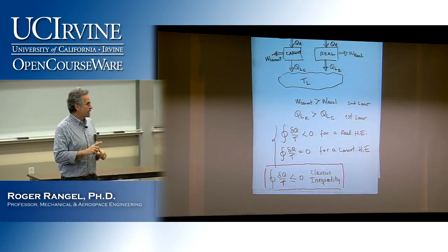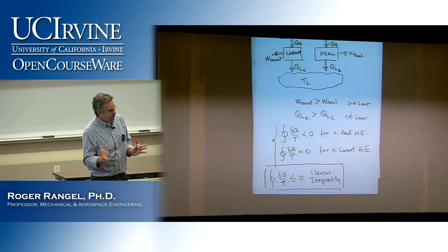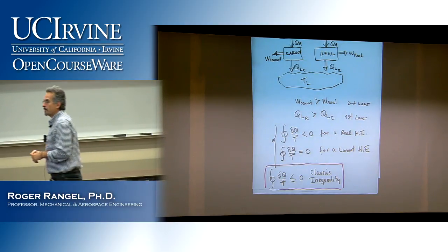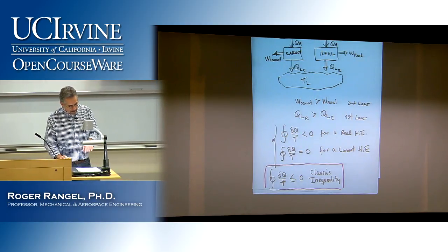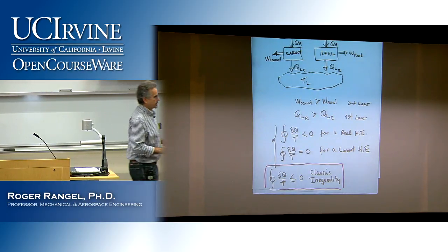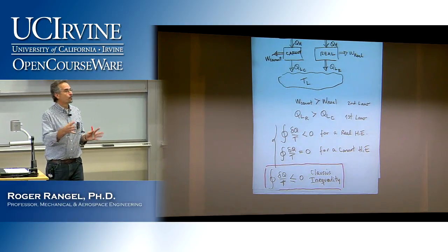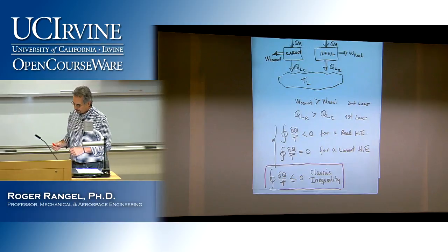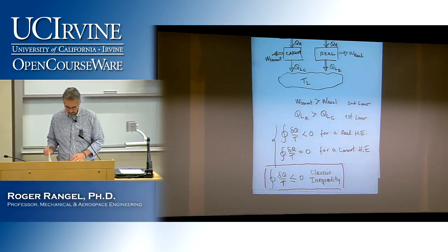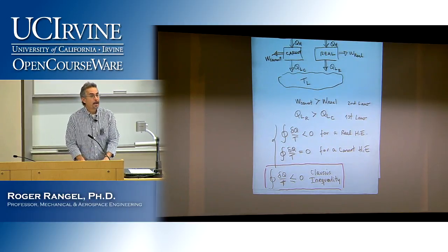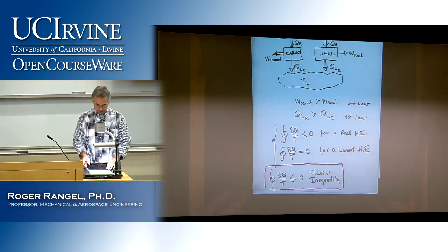However, keep this in mind, ideal cycles don't really exist. Carnot cycles are just an imaginary cycle. So that means that for any real cycle, the integral of delta Q over T is less than 0, always. So this is the second law of thermodynamics, one way to write it as an equation. All right, any questions? So now, let's see how this leads to the property called entropy.